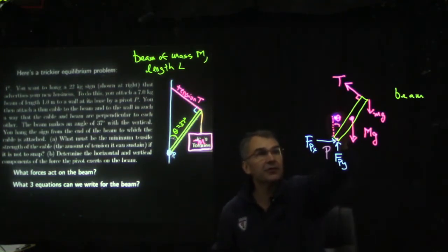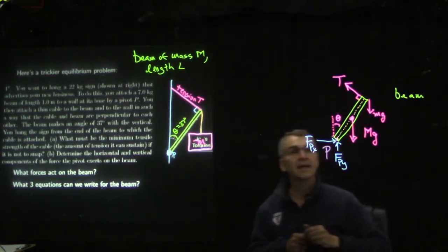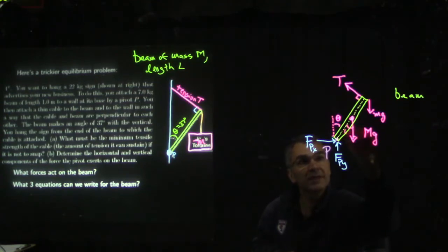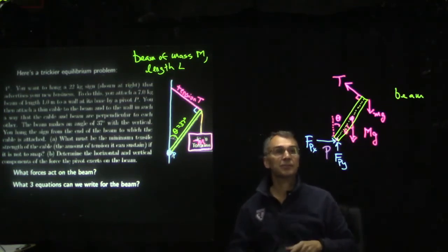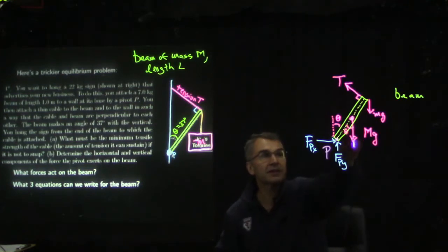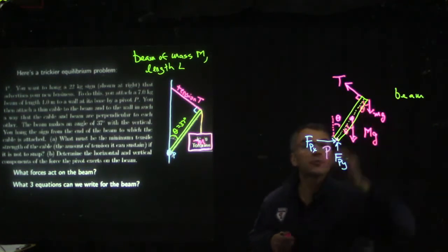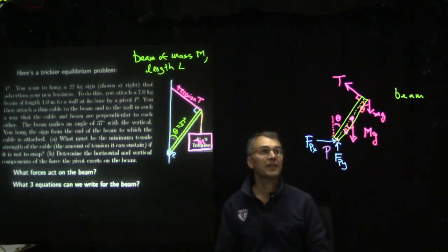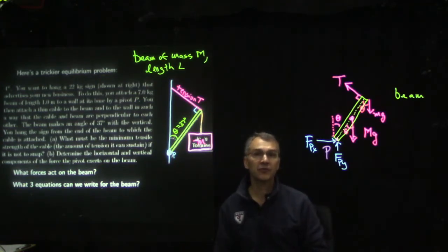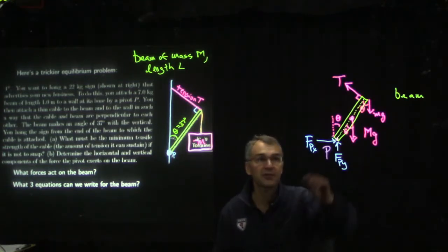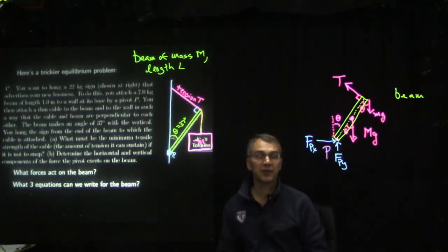And then this is an angle theta from the vertical down to the axis of the beam. And then I think this must also be that same angle theta from the axis of the beam to the vertical gravity line. And therefore this must also be that same angle theta. One thing that's tricky is in this problem, theta is measured with respect to the vertical. So when we use our trigonometry functions, horizontal distances will have a sine theta in them, and vertical distances will have a cosine theta in them because we're measuring theta with respect to vertical rather than with respect to horizontal.